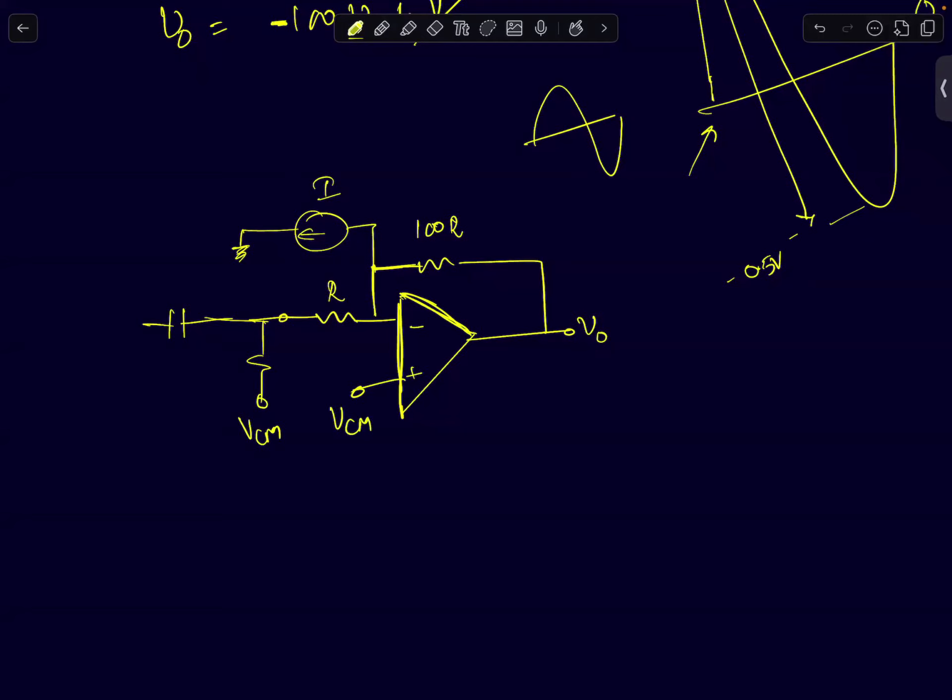We'll come back to those processings later. But I'm just illustrating an example. Forget about the current source being ideal or not. I think one of you asked me a question sometime back: because the common mode node voltage will be at 0, does this create a problem for the current source? Yes, it does. But here I'm assuming for analysis purposes that this is an ideal current source.